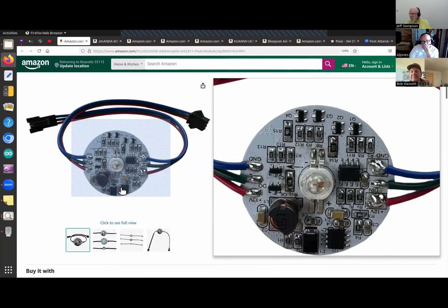And then down at the bottom, there seems to be a switching converter that converts the incoming voltage, which I think they say runs on 12 volts. So it probably converts 12 volts down to 5 volts. And then all these other parts on the board are basically building their own current sources to run the 3 LEDs that are on the board.